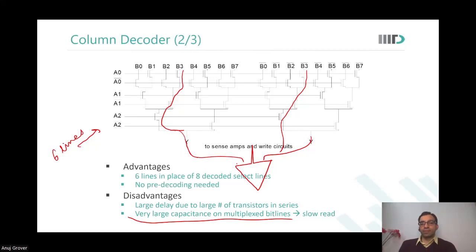See, look at it like this. Now this Y will have to traverse across all the 8 columns. This one signal has to traverse through all the 8 columns. Over here, it has to traverse through 4 columns, and so on. So there are all these additional parasitic capacitances coming into the picture all over the place.